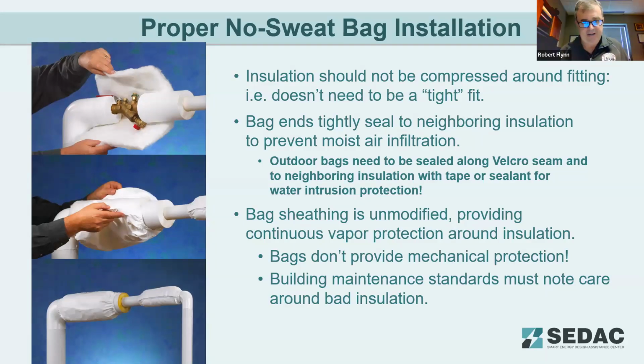And actually in the field, the insulation is very easy to cut when you're dealing with fiberglass. You can actually dig out for something that small. It doesn't cost any time or effectiveness to the job when you can just dig out for the valve as well, or the strainer as well, as long as they can get access to it. Okay, the next one is the proper no sweat bag installation.